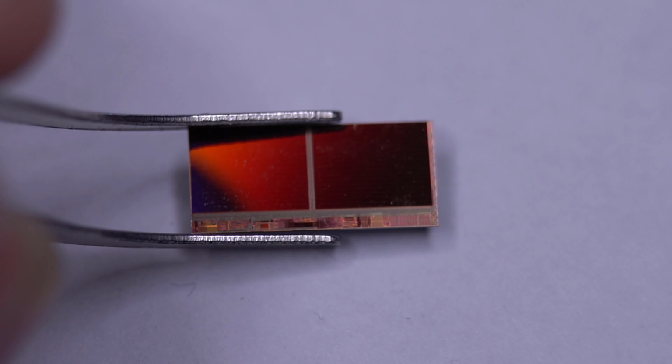However, if the chip was instead oriented on its side, with its surface oriented parallel to the path of the radiation source, it would be reasonable to expect to see fewer unique upset events, but each upset event would likely be able to flip more bits in the chip. This is because the path of the particle would be able to penetrate through a larger number of memory features on the chip. Some cosmic rays originate from the Sun.